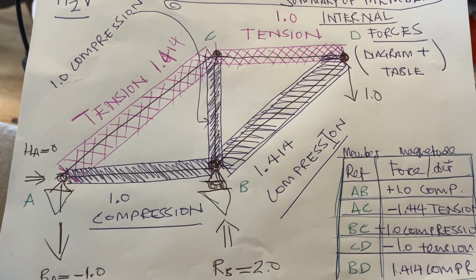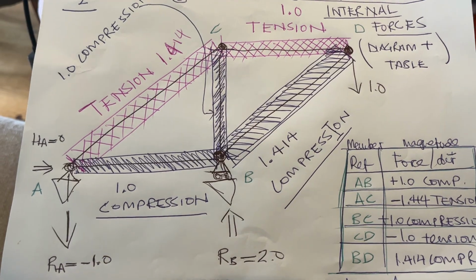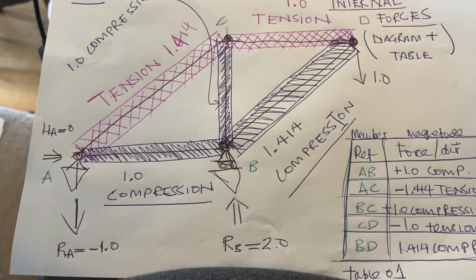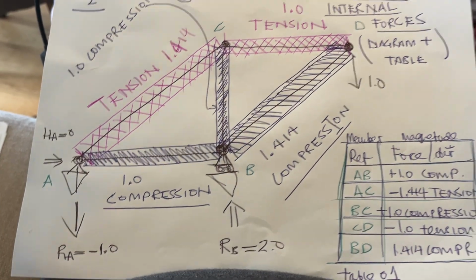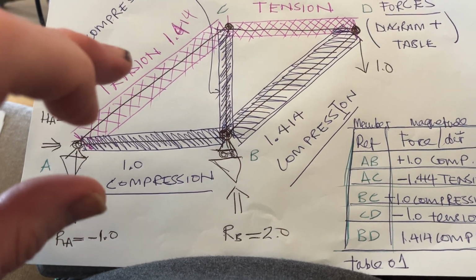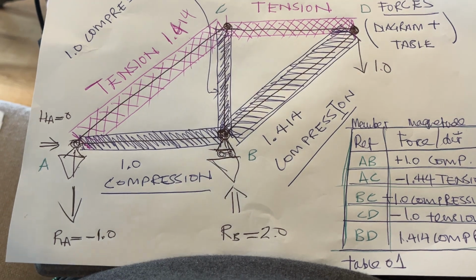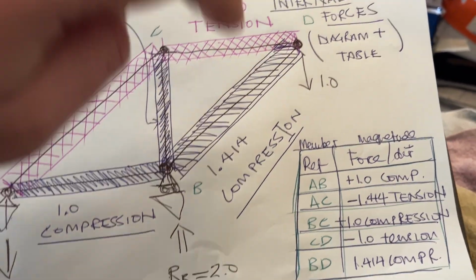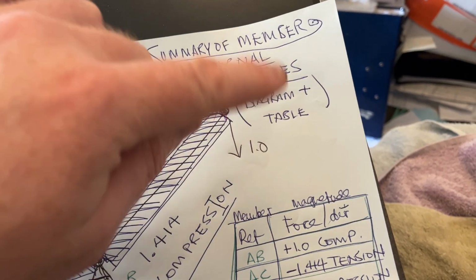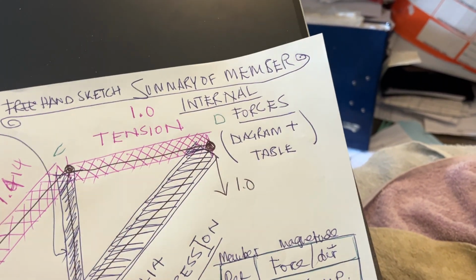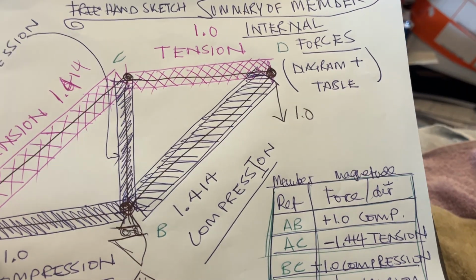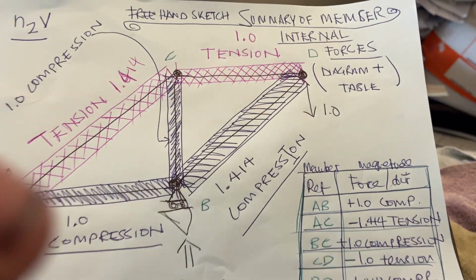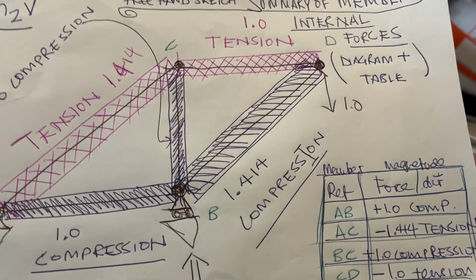And so this is the second part of this deflection solution. For the deflection solution, you need to find the internal forces first, and then you've got to use this matrix, this addition of the unit load. This is the unit load at 1, and then to find the vertical deflection, a unit load, and a horizontal unit load to find the horizontal deflection. So please watch the other videos. I'll put it all in one playlist. Please watch the whole playlist, and then you can understand that